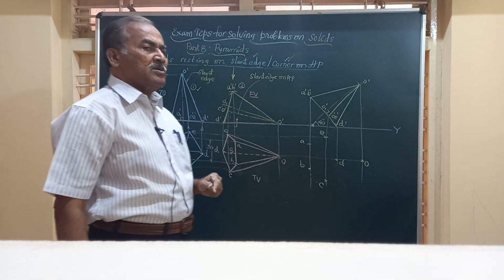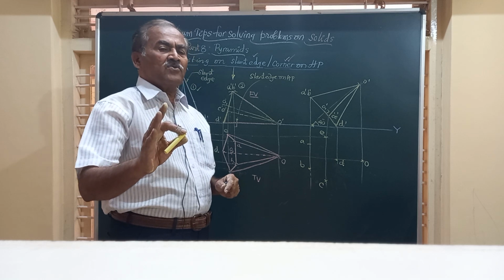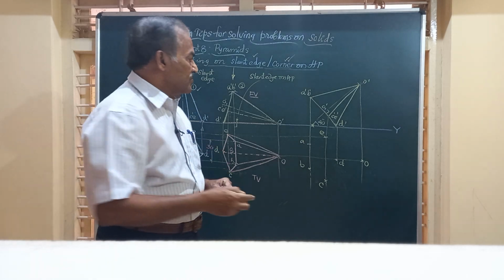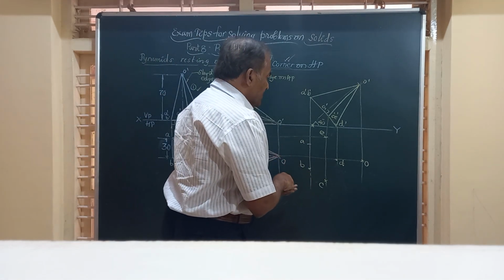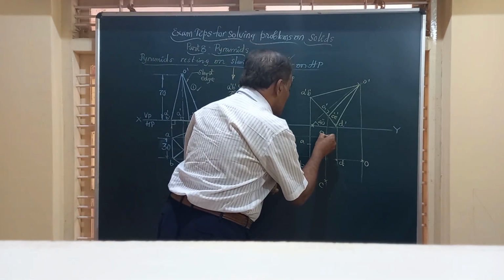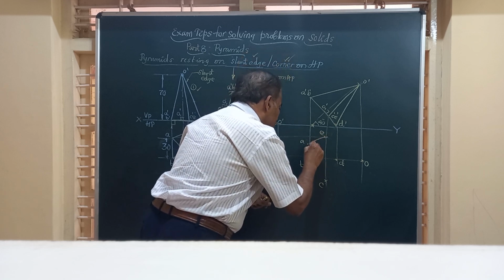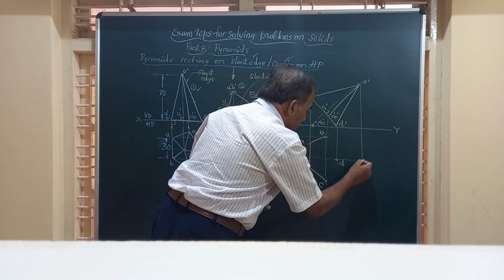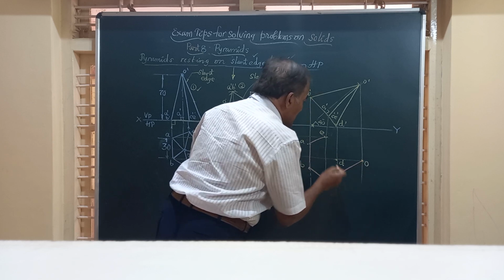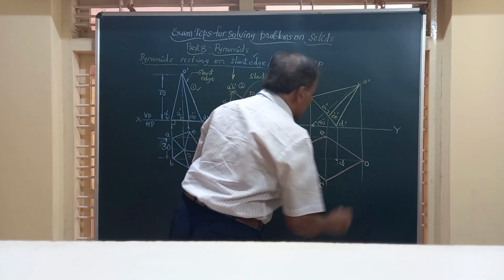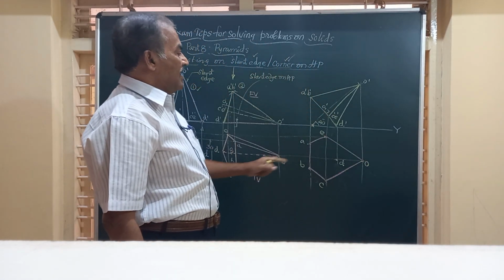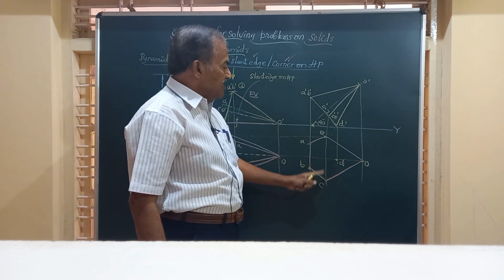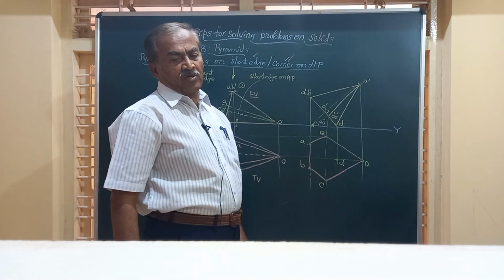Friends, remember, the borders of a solid are always visible in the front and top view. Here if you take this as the figure, the borders are like this. A to E by a full line I have to join, A to B by a full line, B to C full line, the border O to C full line, O to E again a full line. Friends, I have joined the vertex O to the corners A, B, C, E. Only D is left over now, friend.